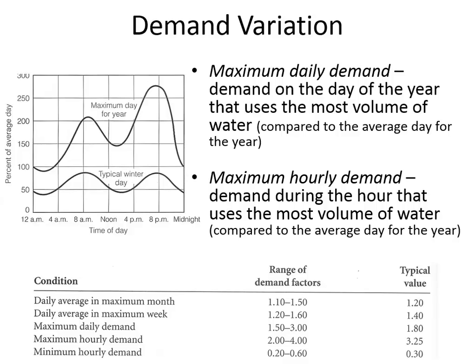So we'll have a class period where I spend some time teaching you the procedure for designing a reservoir, and a big part of it is understanding people's water use patterns. Because on that map where I pointed out there's a spring up in the hills, that spring can't turn up and turn down to satisfy water demands. There's a continual flow of water out of that spring that doesn't vary, and so you have to have a water tank to make up the difference between how much is coming from the spring and how much people are demanding at different times of the day.